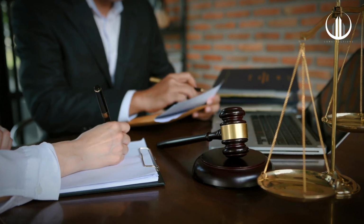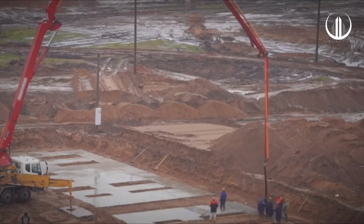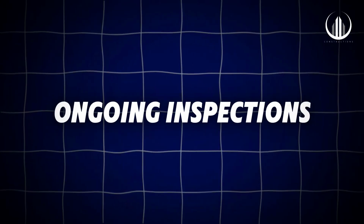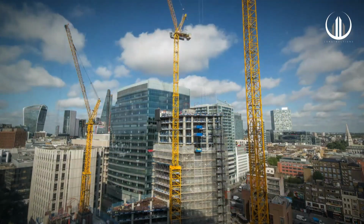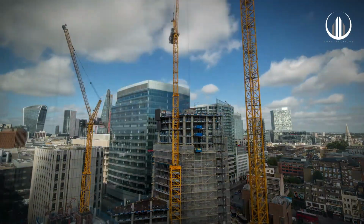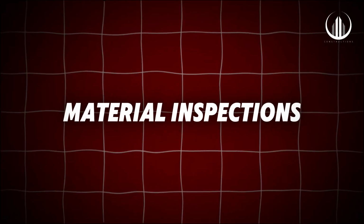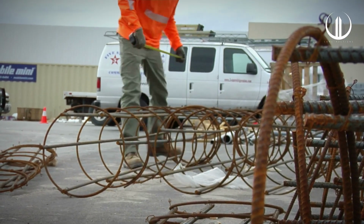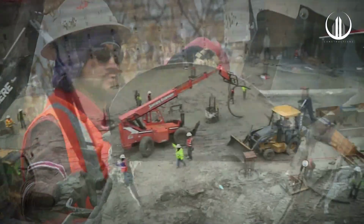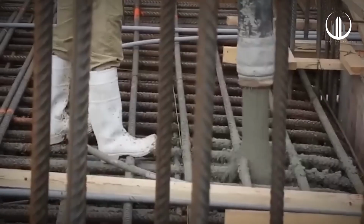Ensure that all necessary permits are in place. Review the construction site for safety and readiness. Ongoing inspections. Daily or weekly inspections. Conduct regular checks on site activities to ensure compliance with safety standards and quality expectations. Material inspections. Before any materials are used, inspect them for compliance with specifications. This might involve checking for the correct type, quality, and certification of materials, e.g., concrete strength, steel reinforcement.